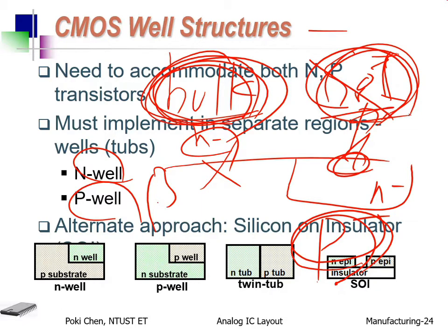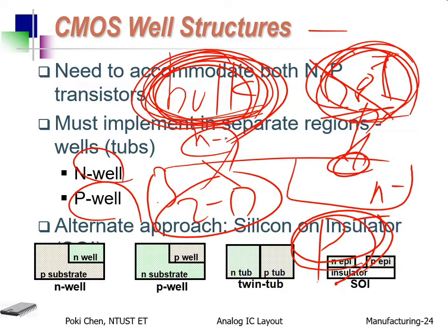You need to pay for an extra process for SOI, right? It means it's more expensive and harder to develop. So for our two-dimensional MOSFETs, TSMC and UMC only focus on bulk. Even though TSMC provides some SOI fabrication services, it never became mainstream. It never was for the mainstream market.